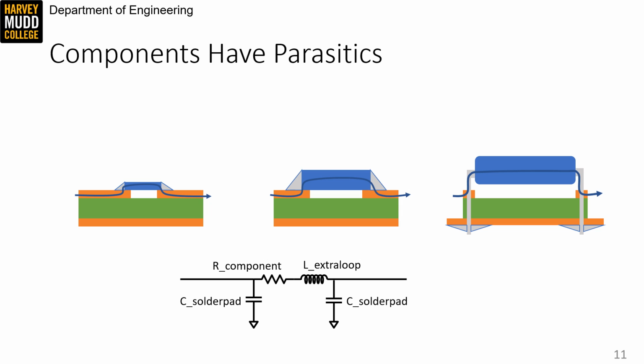Through-hole components present some special hazards for RF designs. They're notorious sources of radiation and coupling because currents in through-hole components can be very far from the ground plane, and because the wires that poke through a circuit board can create reflections at really high frequencies. And finally, because the wire leads are often poorly controlled impedances that look like little transmission lines. The wire leads can be rich sources of radiation if you're unlucky in your layout.